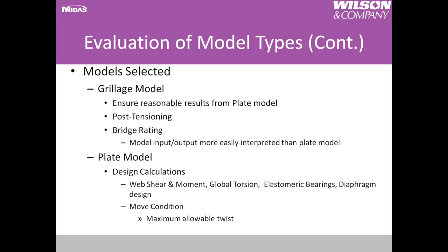The plate model was used mainly for the design calculations, including web shear and moment, global torsion, the elastomeric bearings, and the diaphragm design. This model also came into play for the move condition. I feel it was very important when considering this move condition, since it did do a good job considering the different variables at play for this bridge.